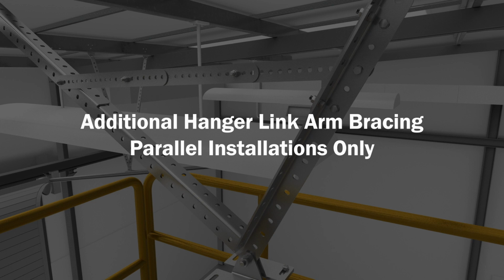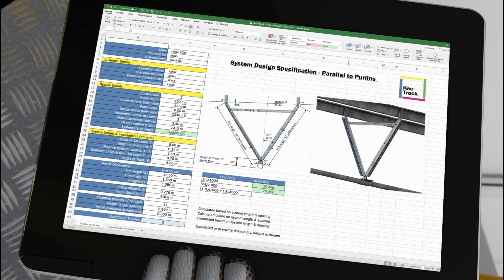Additional hanger link arm bracing. Parallel installations only. For Kee Track installed parallel with the purlins, additional hanger link arm braces must be added, positioned between the individual hanger link arms. Working from the Kee Track system design specification, identify the individual bracing components required and their assembled center-to-center length. In this example, for brace XY, the following components are needed: one TLA 1000 and one TLA 500 with a corresponding brace length of 4 feet 5 inches.